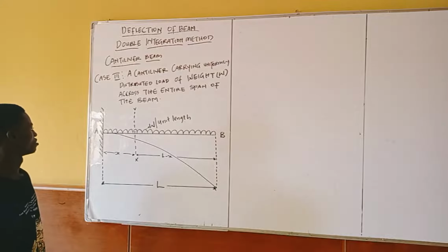So I'm going to have the load as W times L minus x, because when I'm combining to a point load, the weight per unit length, you need to multiply by length, you understand? So W L minus x, then multiply by L minus x over 2, since it is acting at the center of this point.